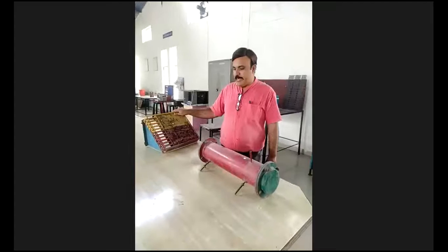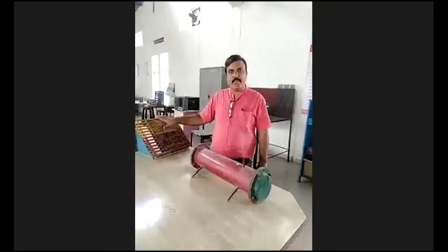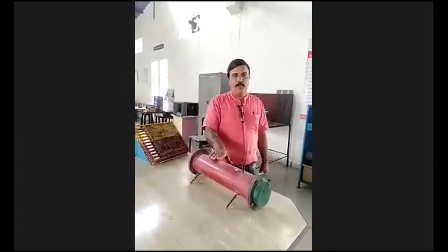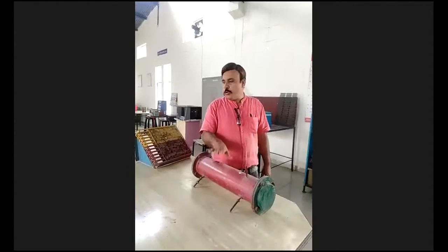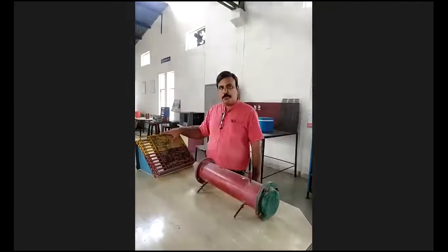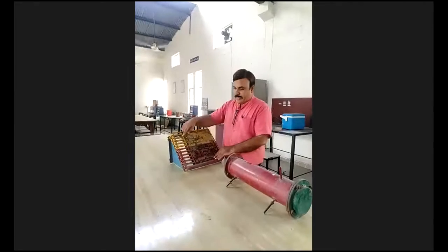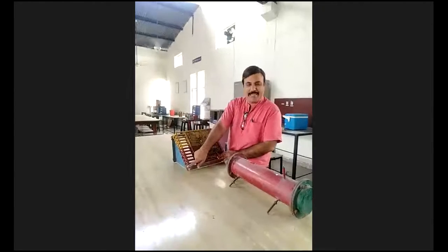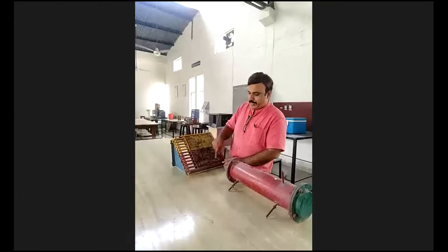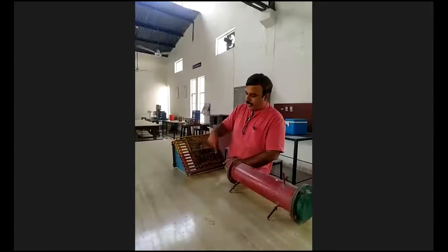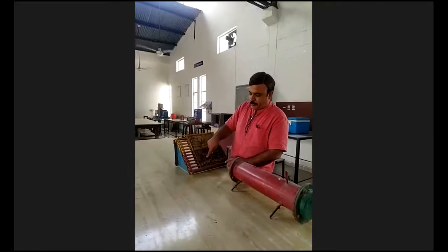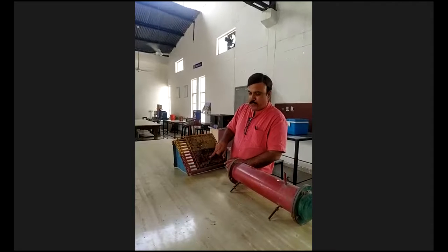So we have this type of condenser. Fin type condensers are also there, and shell and tube type condensers are also there. So look at this finned tube type condenser. Look at the vapor which is coming from your compressor. When it moves from the lower side to the upper side, it will continuously give its heat to these things.